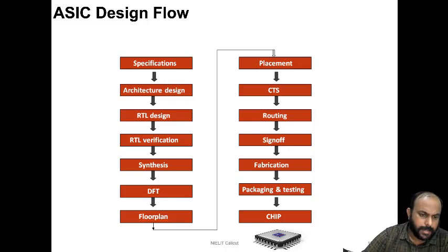RTL designs are basically descriptions of your circuit, or descriptions of your hardware, written in hardware description languages like VHDL, Verilog HDL, SystemC, or SystemVerilog and so on. RTL here stands for Register Transfer Level. It is a way of describing hardware so that it can be converted to a real circuit structure.